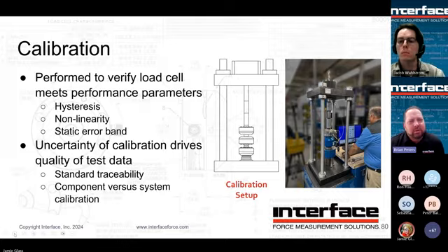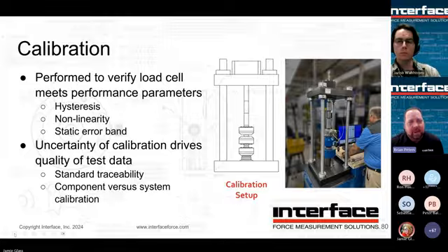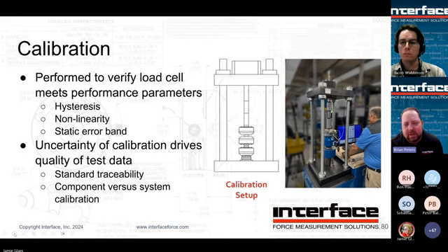And then from there, we go to hydraulic reference standard cal, which is what's depicted here, where we're using a couple load cells to track. So in that schematic there, we have a load frame. That top unit would be the DUT, or the unit being calibrated. The unit below that would typically be our calibration standard, where we have very high confidence in that. That goes back to NIST for calibration. Some of our standards in our lab are older than 40 years, believe it or not. So we have binders and binders of history and extreme confidence in those standards. And then depicted under that would be the hydraulic control sensor for the hydraulic frame. So that one would be controlling the actuator to monitor the applied force. So this is a good depiction here.